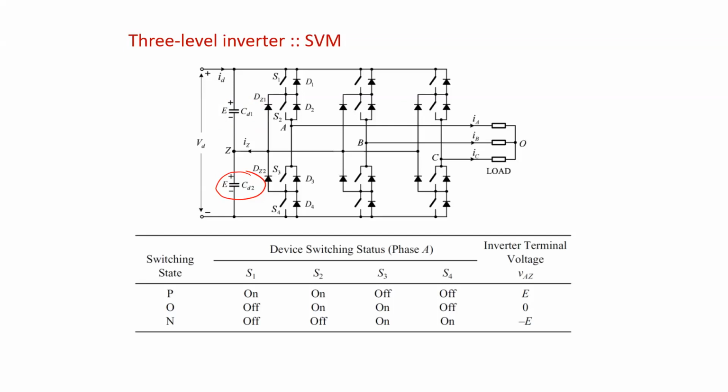So there will be some deviation in the voltages, and in the charging and discharging periods also. That creates an unbalance in the capacitor voltages, right? Another cause is inconsistency in the switching characteristics, as we already discussed. When you require one voltage, if you continuously turn on the upper one or the lower one, that causes some inconsistency in the capacitor voltages.